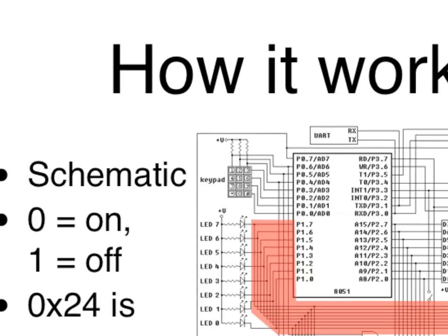See, 8051. There. That's your microcontroller. And a microcontroller is a little microprocessor on the inside, but it has input and output interfaces on the outside. And you see on its lower left, there's P1.7, P1.6, P1.5, all the way down to P1.0, right?